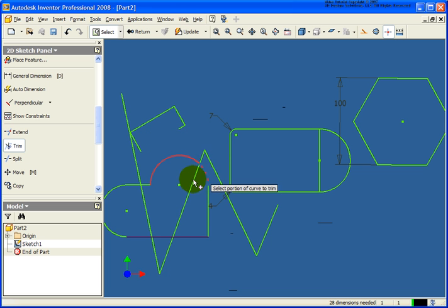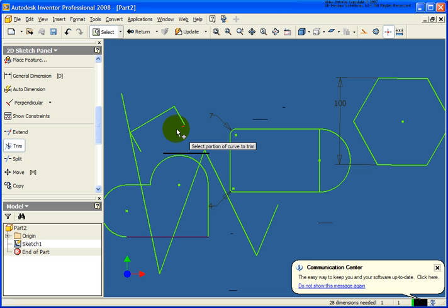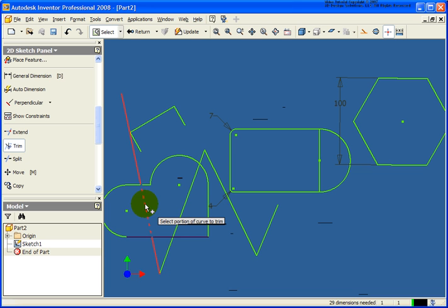But you notice what Inventor is doing, it's taking a look at all the different line segments, and where another line would intersect that, it's going to cut itself short. So in this case, if I selected that other line segment that was left, you can actually erase a given line. So let's continue our adventure down here. I'm going to select inside that shape to trim that back out. And you can see it goes pretty quickly here, but the more line segments you have, the more trimming that it's going to be required to do.